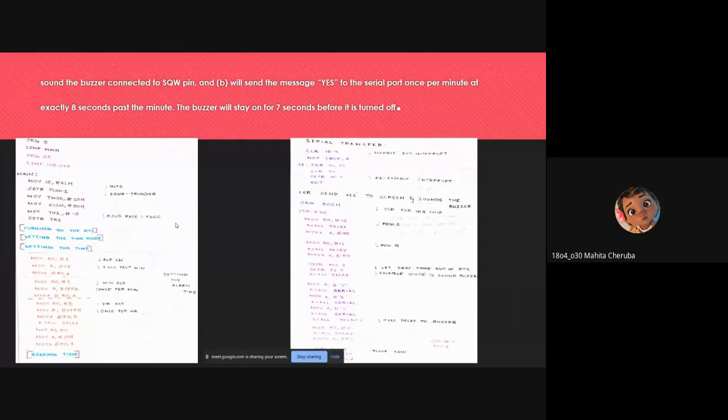And then we are moving our A value into the SBUF, and then we are monitoring our transmit flag. After it is completed, we are clearing it and keeping it ready for the next transmit to occur. And as you can see, once the transmit flag completes its role, we are again setting our external interrupt to 1, and then we are returning to the main program.